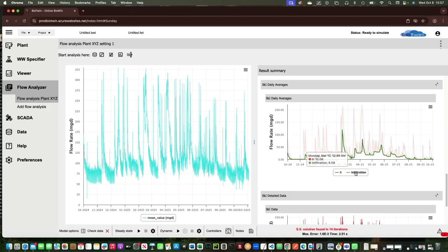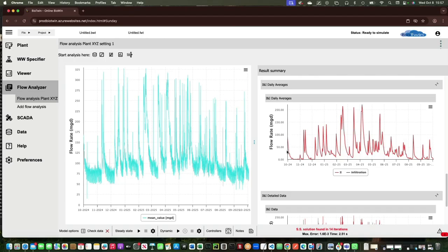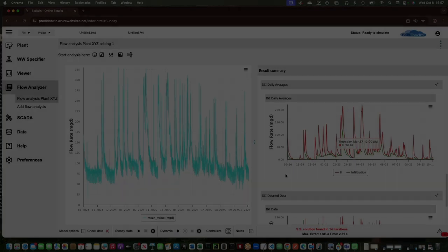So if I click on infiltration, and just to hide it, if I were to trace a line on the bottom of this I&I trend, that indicates to some degree the trend of your infiltration flow. Now, obviously, it's a subjective analysis, but it is just one of the ways that people have estimated I&I and infiltration in the past.